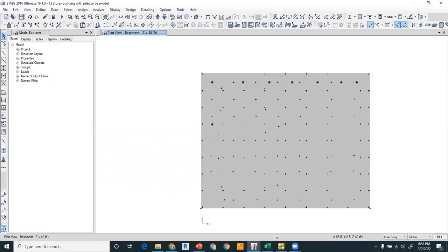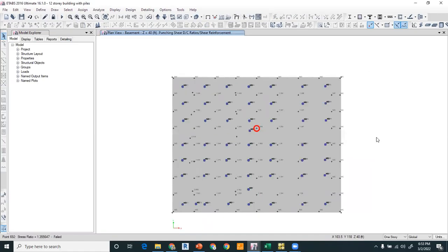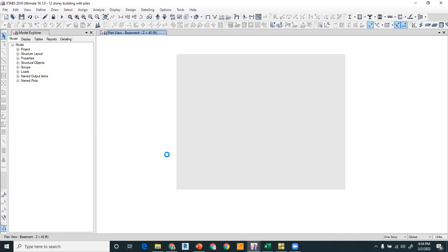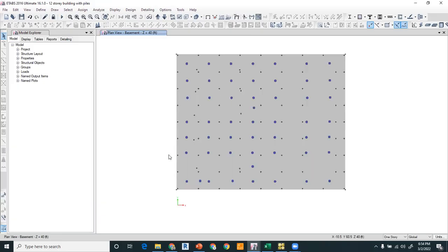after that, let me show you the model which I have already done, to save time, because remember that the design of the model in ETABS will take a lot of time, right? After the division into segments and assigning springs, the file will become very heavy. When I analyzed this structure, it took 2 hours to analyze this model, right? So try to keep the segments as large as you can.